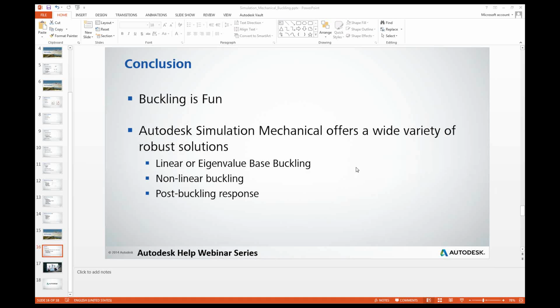And I'm assuming you're talking about the load combination here. As far as the load combination, no, you can't combine these two different analysis types. But if you're asking whether the response spectrum analysis captures buckling, I would say no. They would have to be done separately.